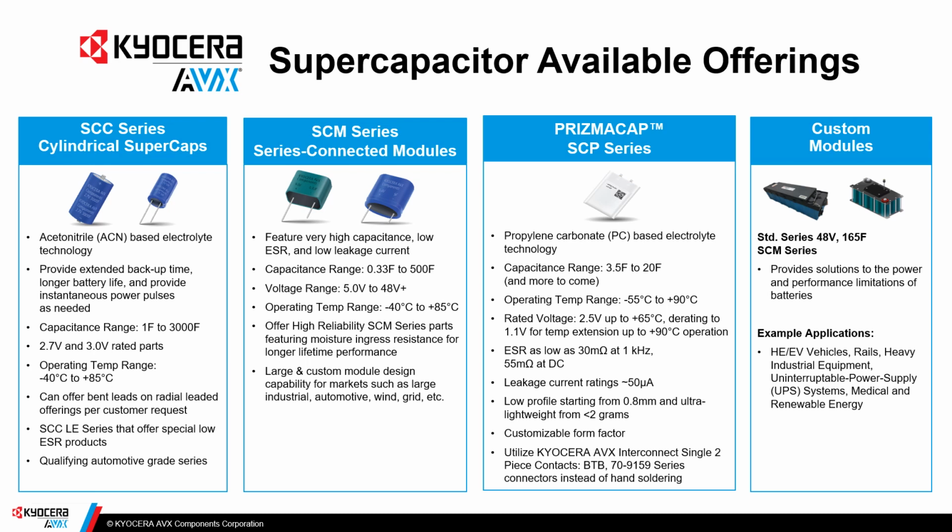Of course, the capacitance drops, the ESR doubles, but in many cases, having a single component to drop on a board and to be balanced or unbalanced, either passively balanced, actively balanced, or unbalanced should the end users want, those are good options. Operating temperature range is the same. Voltage ranges could commonly be up to 48 volts, up to 500 farads. They're really easy to use. The parts on the left of the second column are essentially a shell, which is backfilled.